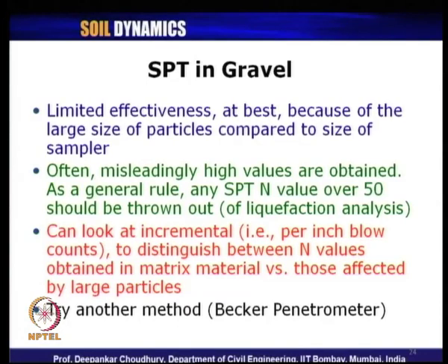That will give us the confidence whether it is truly a very stiff soil where liquefaction analysis is not required, or it is just at a particular location, because of the presence of large particles, that there is suddenly a high N value. In that case, if you discard the liquefaction analysis, that will not be proper.